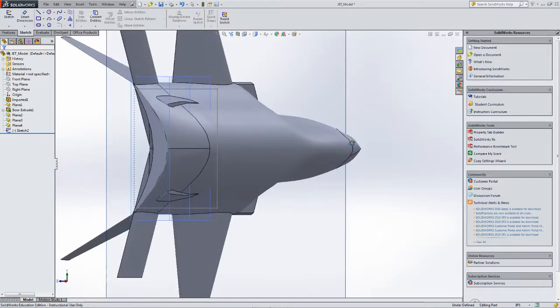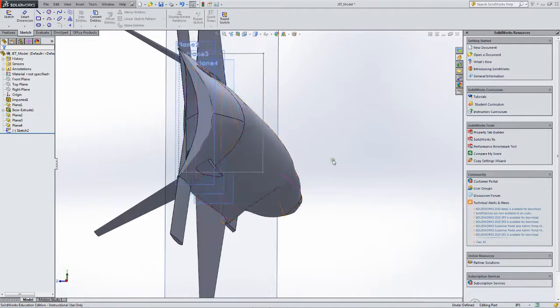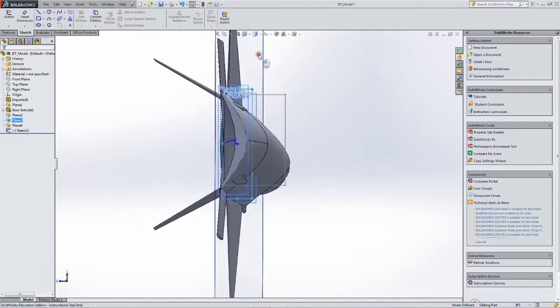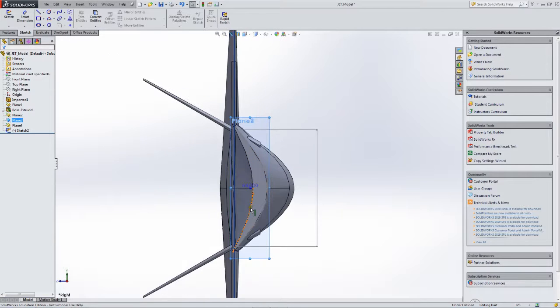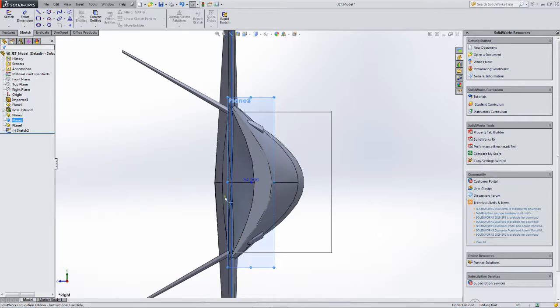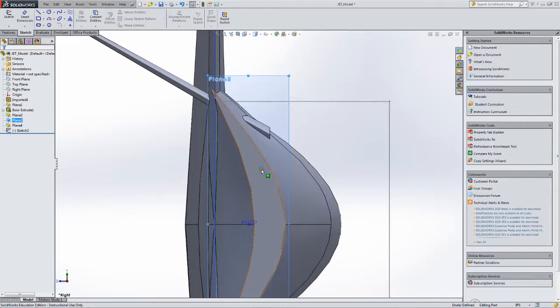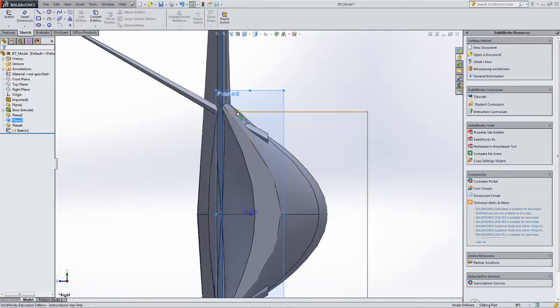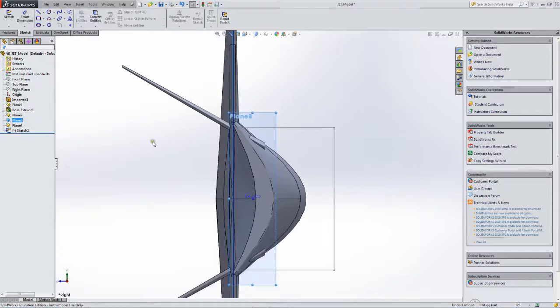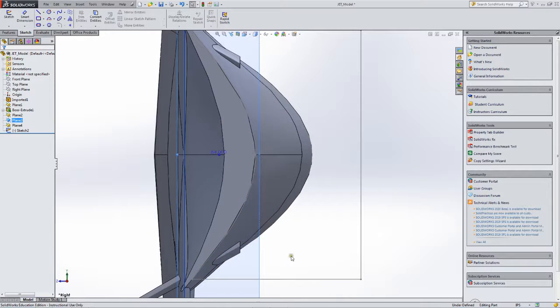We're going to do the same thing in this next plane. To make sure I selected the right plane, I rotated the body so I could see it better. Make sure I'm on plane 2 or plane 3, and then get that rear view, which is a side view in CAD nomenclature. Alright, so here's the next point I have to follow. Alright, so I'm going to start up here. Well, no, I started the center line. That'd be better. The same way I did the other one. Okay, I'm going to follow that black line.